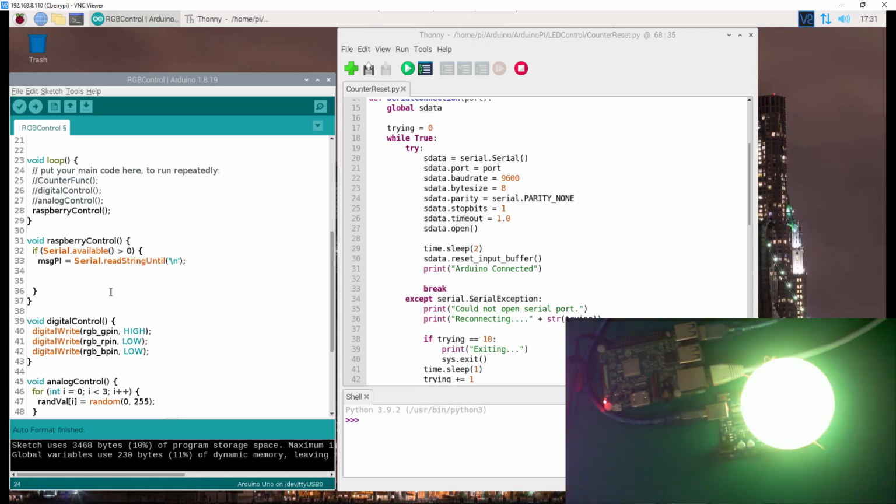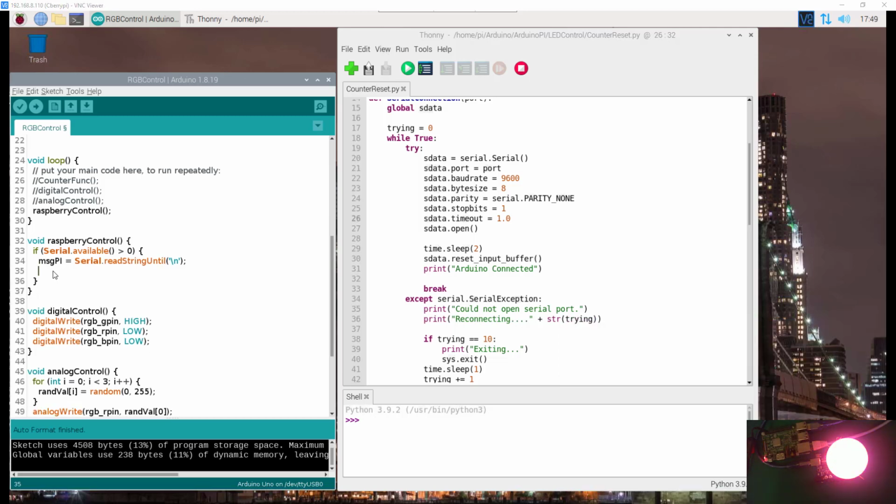Now we can process it. In the previous tutorial, we displayed the message onto the LCD. Okay, but we don't have to do that now. If you want to see how we implemented it, please watch the previous tutorials. Right, now the simplest way to handle data from the serial stream here is to implement an if-else ladder. So I'm going to create another if statement here.